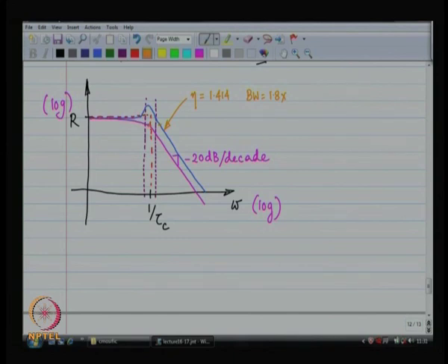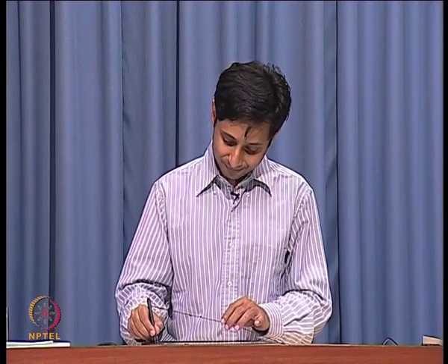However, I ended up with a substantial amount of peaking. So, this phenomenon is called peaking. Why did this happen? This happened because I was over aggressive, because of the pair of complex conjugate poles being rather close to the j omega axis. And the way this can be avoided is by pulling the poles away from the j omega axis. In other words, you reduce your aggressiveness. So, let me increase the value of eta and I will get something better.